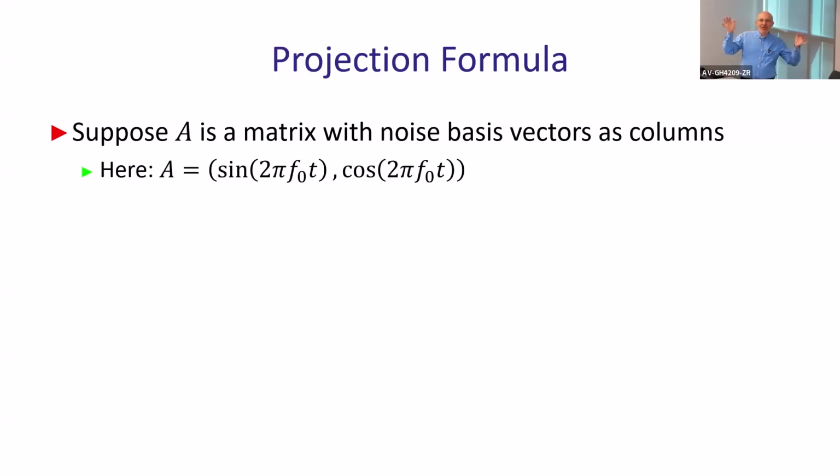You assume it is white noise, maybe broadband, or you assume this is some particular pink noise or shot noise. It depends on the physics of the problem, right? So you assume something about the noise, but you don't know much about it. In that case, this is the other way around. You know everything about noise, and you don't know anything about the signal.